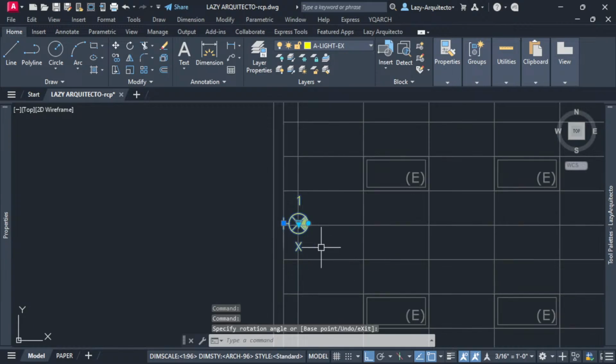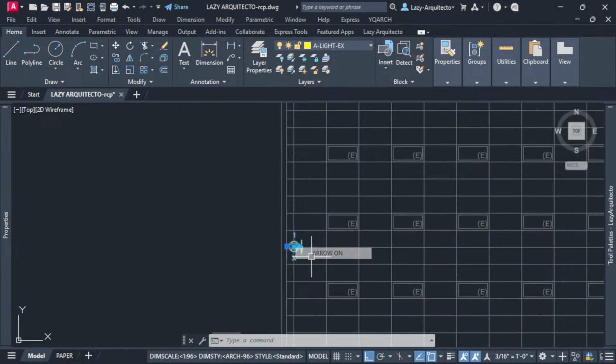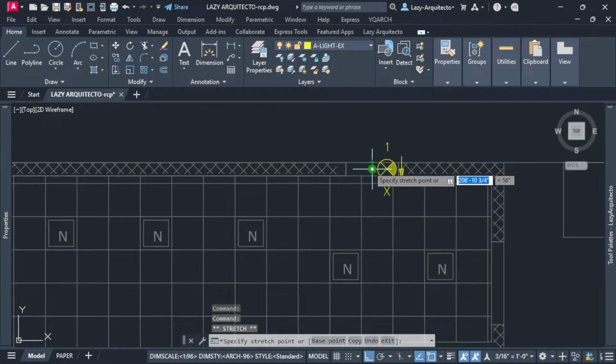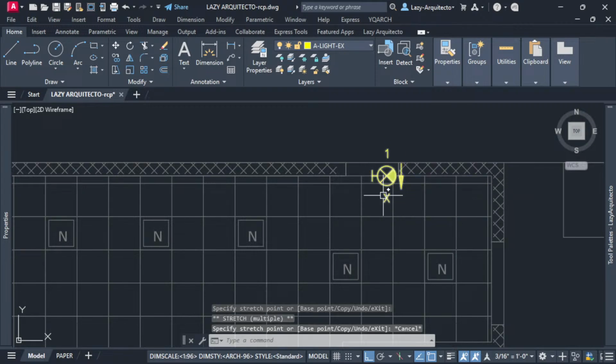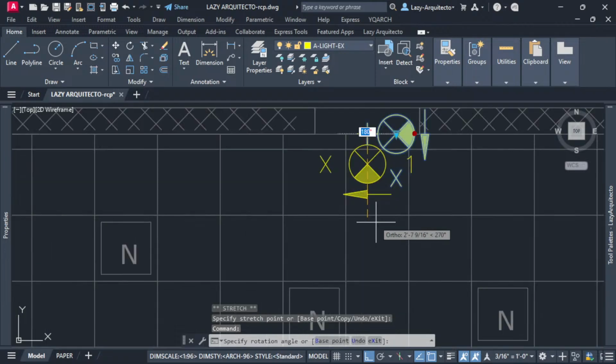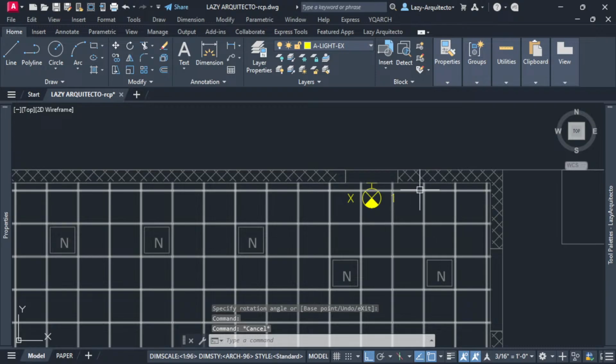And great, our grip is now being kept center always. And of course I need an arrow here, so I'll use an arrow, and I can keep implementing my exit light quickly and easily, again with this quick dynamic block that we just created to simplify this task.